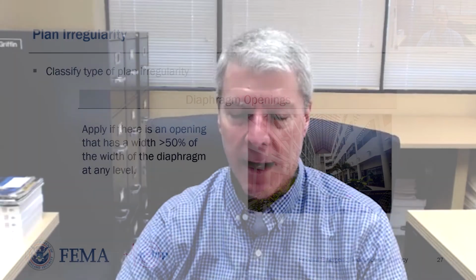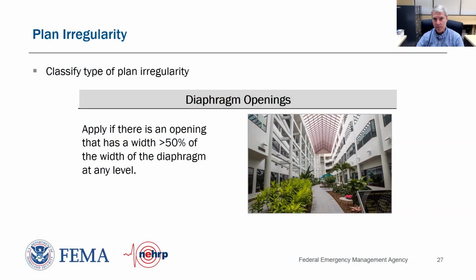That's the problem. Again, it's easy to identify visually, and the criterion is if we've got a diaphragm opening that encompasses more than 50% of the width of the diaphragm in either direction, then this is a potential vulnerability, and we need to flag it as a plan irregularity and score it as such.